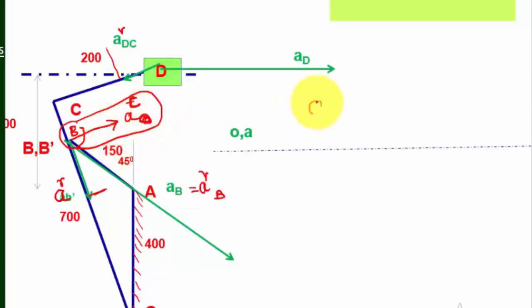So how do you find the AC? AC equal to 2 into V omega. Omega is nothing but angular velocity. V is nothing but velocity of slider. From that you can find the Coriolis component. Whenever a point rotates as well as slides, we must calculate the Coriolis component. Here the point B dash on B rotates as well as slides, so we are calculating the Coriolis component.